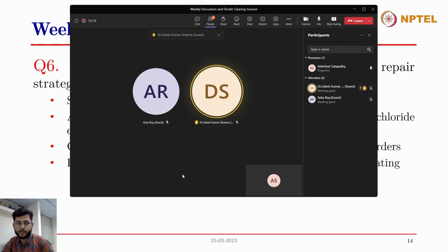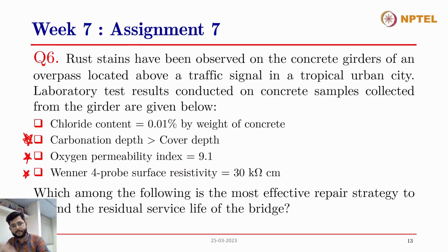Yes, Dr. Nitish. You see, in the problem, the chloride level told is only 0.01% by weight of concrete. This is a low level. Right. So chloride attack is not the major problem. Carbonation depth is more than cover. So it's a case of carbonation.